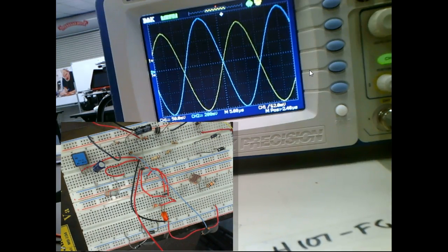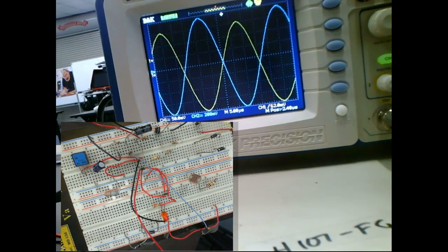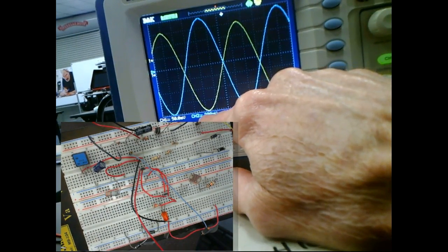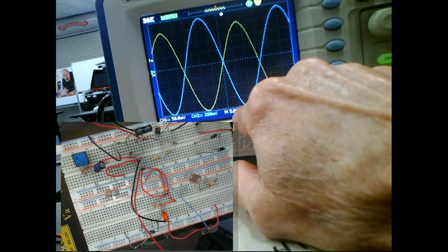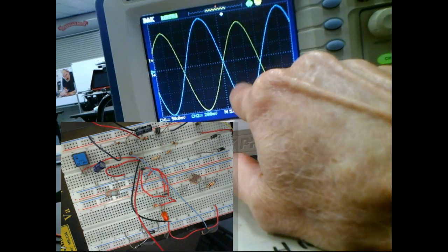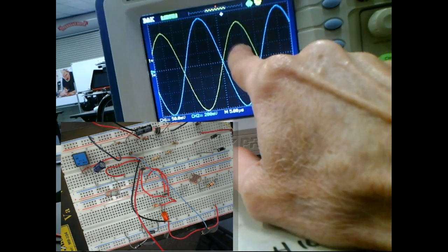So we're still putting 350 millivolts in. If I multiply that by 5, what would that give us? 1 point what? Okay, so this is 200 millivolts per division on my output. So this would be 1, 2, 3, 4, 5, 6, or 200, 400, 600, 800, 1, right?